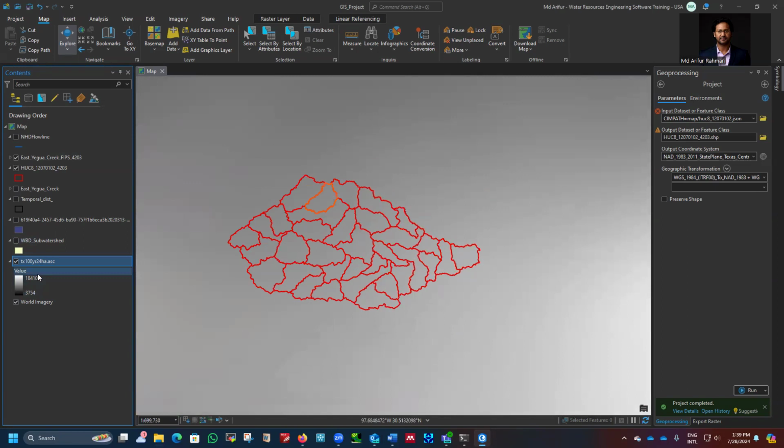But here you can see we have only one value for 100, and we have the same scenario for the other profiles we just downloaded. But we need to run the model, so if we use this one single value, we won't get the distribution. So we have in our CS a temporal distribution factor. We'll apply that factor to generate a 6-minute interval raster from this one single raster for each of the profiles we have here.